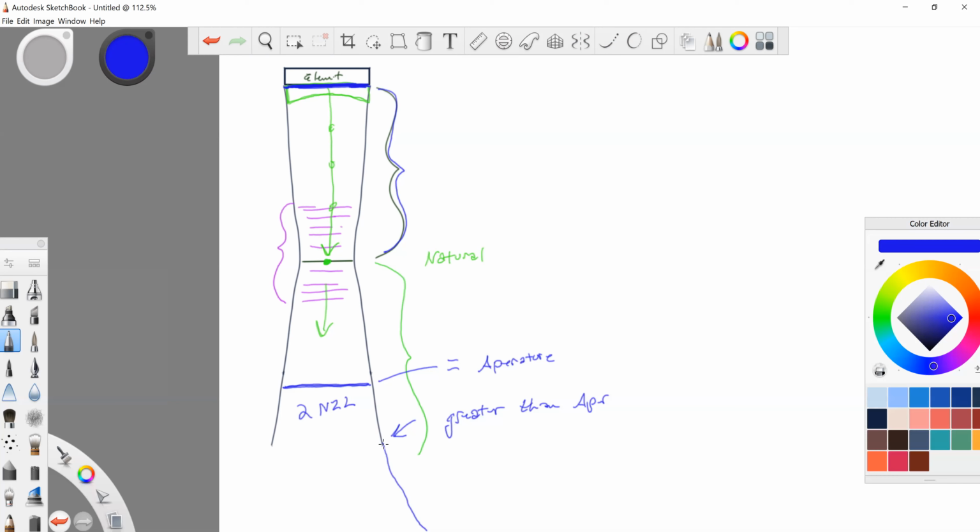then the PZT crystal has a diameter of 16. False. No. If this is 8, because it says the diameter of the sound beam is 8 millimeters at a depth equal to twice the near zone. 2 near zone lengths is 8 millimeters. Then this is 8 millimeters, the width of the aperture. The diameter of the acoustic sound beam produced by the crystal is 8 millimeters at a depth of twice the near zone length. And the same question.